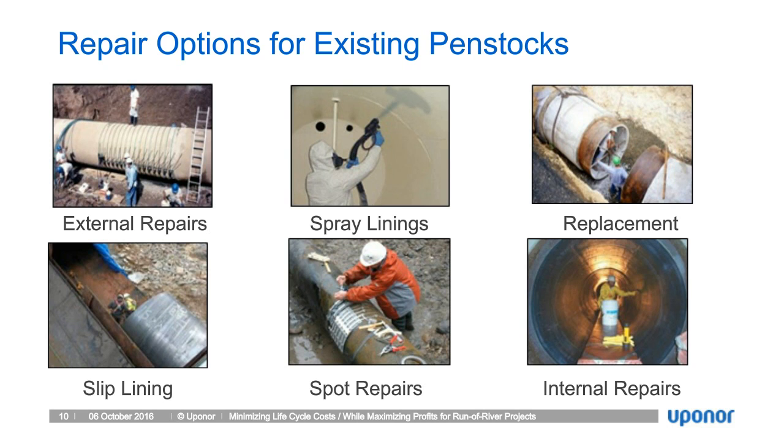And lastly, what we'll be talking about is replacement. Material nowadays, designed specifically for low pressure, high volume applications, can offer such economical sense that the complete penstock line can be replaced and still have a cost savings rather than trying to perform external repairs or slip lining or spot repairs. So replacement can be a much better idea than trying to do repair.